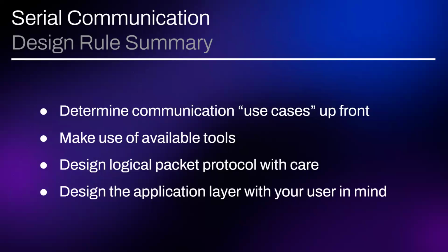The big difference between the 422 and the 485 is you can have multiple masters on a 485. We don't actually utilize that part, but some of the equipment comes by default set to 485. Our range is 1,000 feet or something like that, some ridiculous thing. RS-232 can't go that far, it's like 25 feet or something, and then it falls apart.